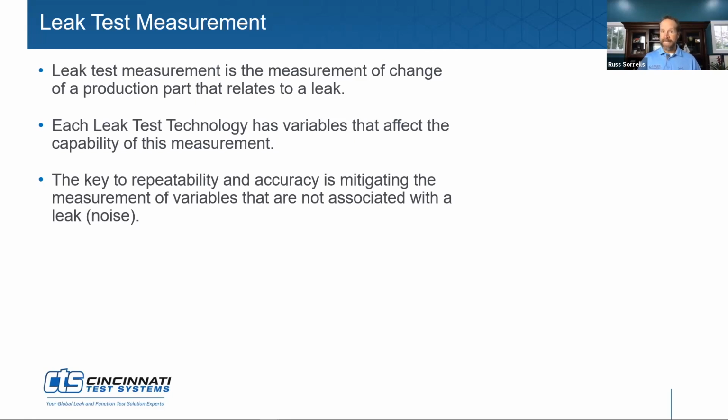So T-A-R-E. If you've ever had a measurement where you're measuring a basket of strawberries, you measure the basket first. So you put it on the scale and you zero the scale. That's called taring. And then you put the strawberries in the basket and you measure the actual weight of the strawberries. Well, leak testing is very similar in that we want to tare out all of those variables and leave ourselves strictly with the measurement of the flow that is coming out of the part.